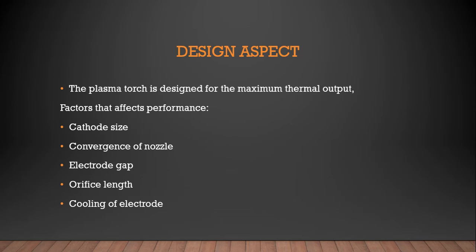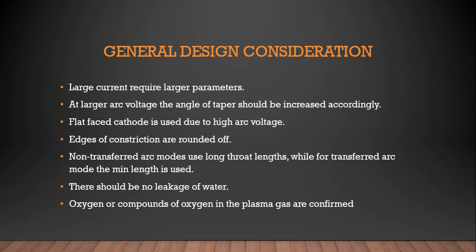Next, we have general design considerations. Large current is required, with large parameters. At large arc voltage, the angle of taper should be increased accordingly. A flat faced cathode is used due to the high arc voltage. Edges of constrictions are rounded off. Non-transferred arc modes use long throat lengths, while for transferred arc mode, the minimum length is used. There should be no leakage of water. Oxygen or compounds of oxygen in the plasma gas are avoided.